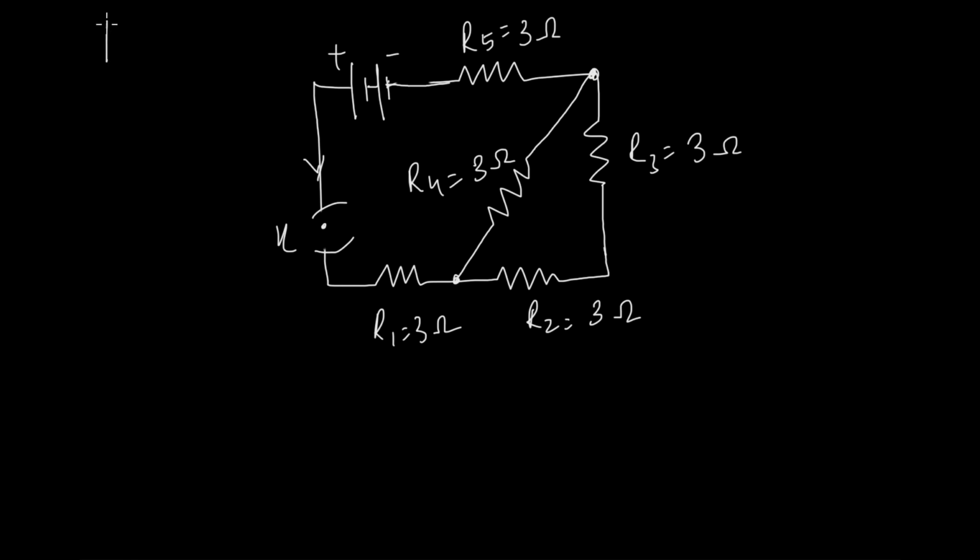Let's do one where both kind of resistors are present together. Here we have to also calculate the total resistance of this circuit. Now this may seem complex to you, which one is in parallel with which, but let me just tell you a very simple way of trying to analyze which resistor is in parallel and which is in series. The method is that you're going to trace the path of current. I'm going to say that the current is flowing in this direction, right, from positive to negative.